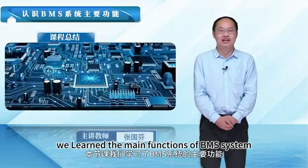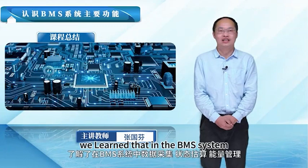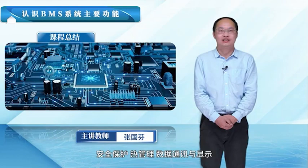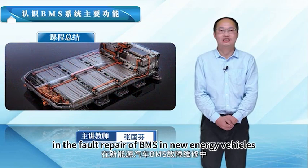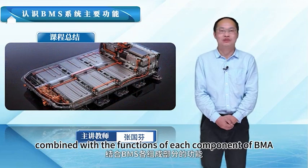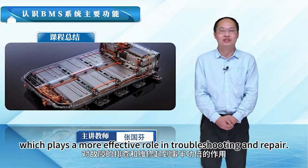In this class, we learned the main functions of the BMS system and the specific functions of each component. We learned how the functions in the BMS system, data acquisition, state estimation, energy management, safety protection, data communication and display, and fault diagnosis, are realized through each component. In the fault repair of BMS in new energy vehicles, you can, according to the fault type, combined with the functions of each component of BMS, detect the corresponding unit, which plays a more effective role in troubleshooting and repair.